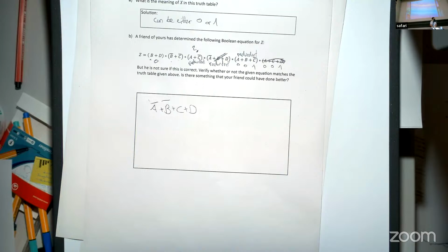You try to draw large circles and also manipulate the axis in a way that helps your case. Here it's very difficult to say. What you're saying is correct. It's a 4-term literal, right? There was probably one where you could have merged it into the others. You could be sharp and see it. You could do some Boolean manipulations and see it. The K-map is a more visual way to see it faster.